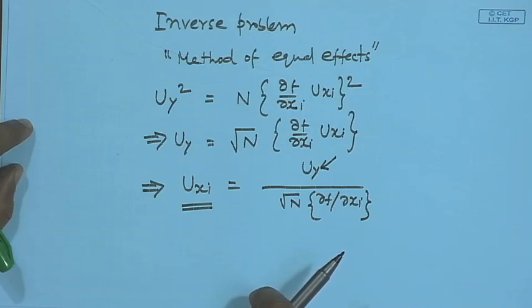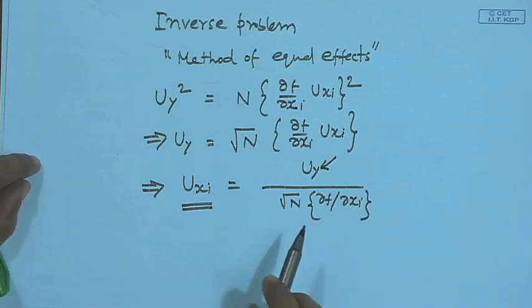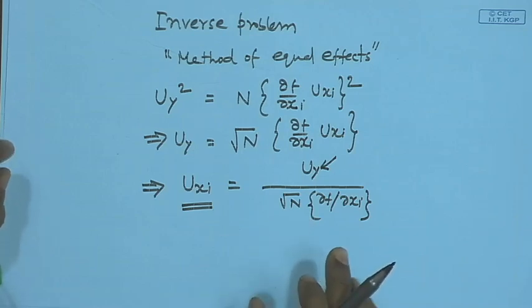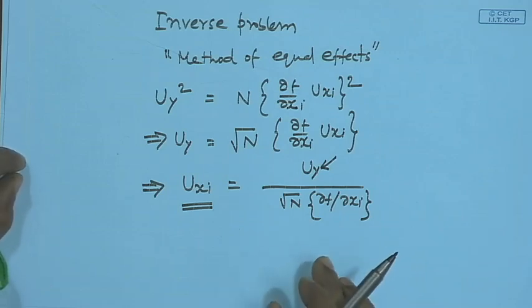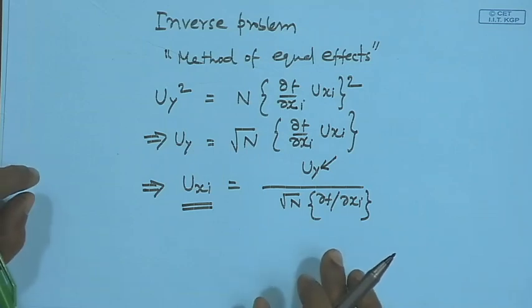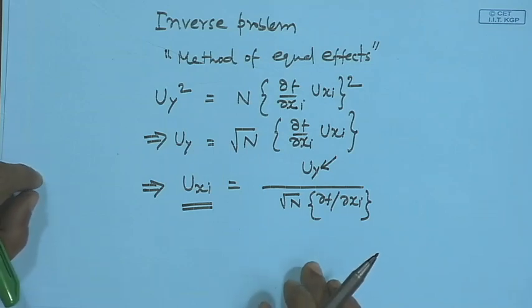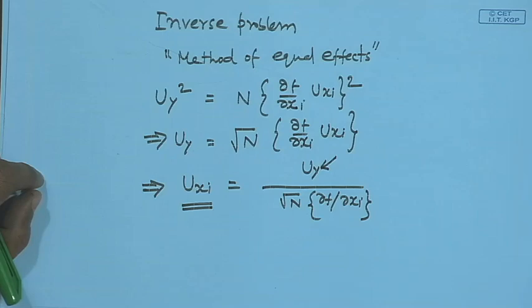If one or more requirements cannot be met, we should check if some of our instruments are better than the above equation requires. If that is the case, then you can relax the requirement that we cannot meet. Ultimately, the overall accuracy must be met.